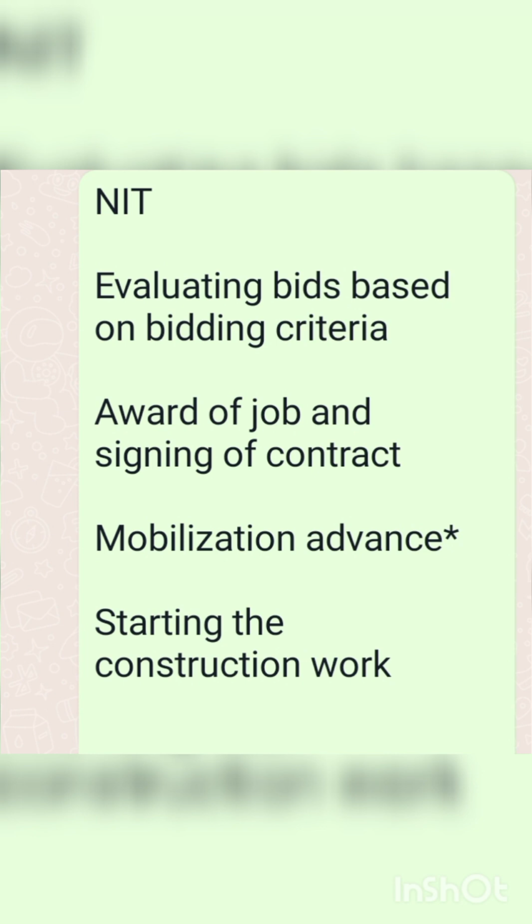So we first publish the NIT to different media, then we evaluate bids based on bidding criteria, then award the job and sign the contract, then we give mobilization advance if required, then start the construction work.